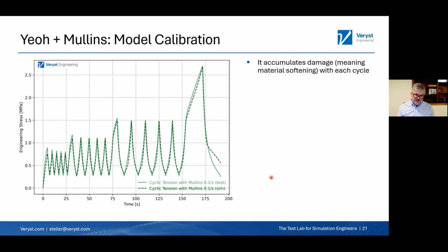That's a different type of damage. I wouldn't do that in Ansys Mechanical, because I will only do that in explicit simulations, and Ansys Mechanical is an implicit solver. There are ways to do it in Ansys Mechanical, but it's not something that I've spent a lot of time on, so I think it's a little out of scope here.